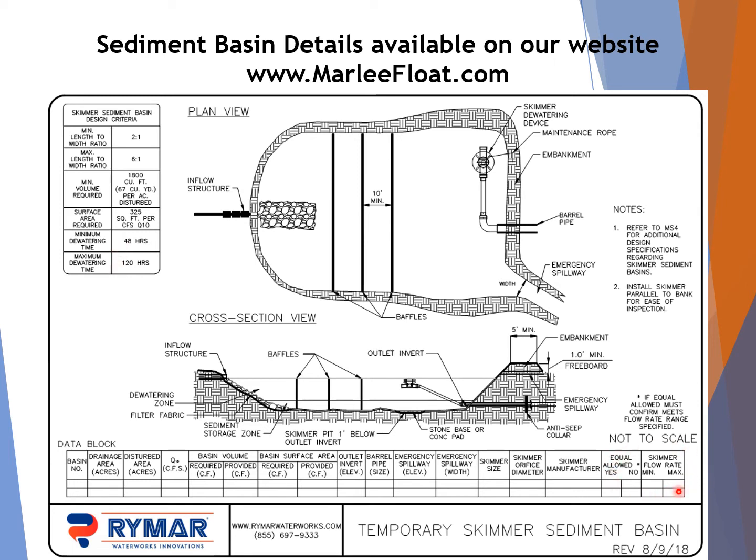By putting this on your detail during the review process, if the contractor or owner decide they want to use a different skimmer or different size skimmer, as long as it meets the range specified, it should not have to go back through a full review and simply be a shop drawing. Again, we have this version without a riser structure and with the riser structure available on our website.